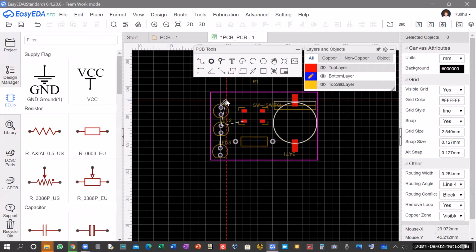Again, avoid 90-degree turns. Take 45-degree multiple turns. That is a benefit for your PCB. Now click on this point. You can also use its auto route feature, but I honestly don't prefer it. And it's also not that good that you can always rely on it.